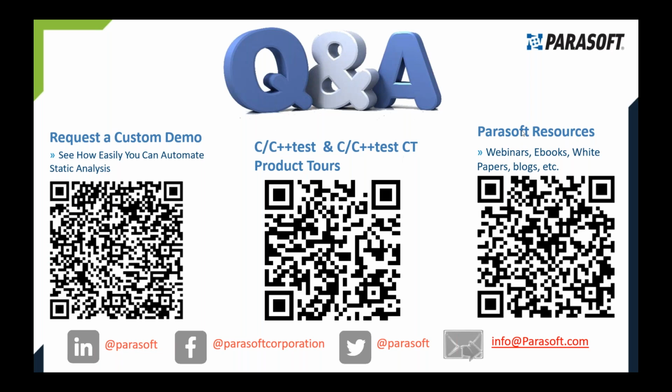So we've got questions here. Why is it that a test tool cannot be certified by TÜV? So that's a good question. In avionics systems and for DO-178C, because of the tool itself, you have to ensure that it does not bring in any issues or any false information or anything like that. You actually have to qualify it within the development environment, within the development ecosystem. So having it certified by a third party, say something like TÜV SÜD, which industries like automotive and medical and rail and so forth accept, for avionics systems, that's not enough. So you have to qualify the tool within the development environment.